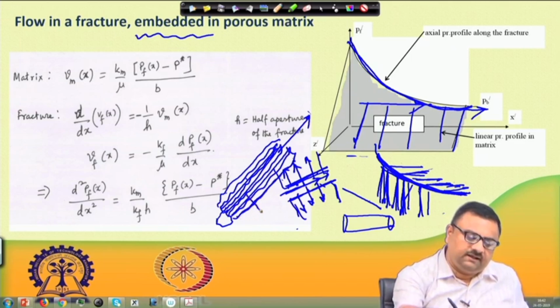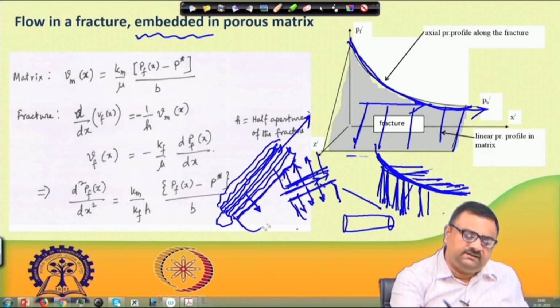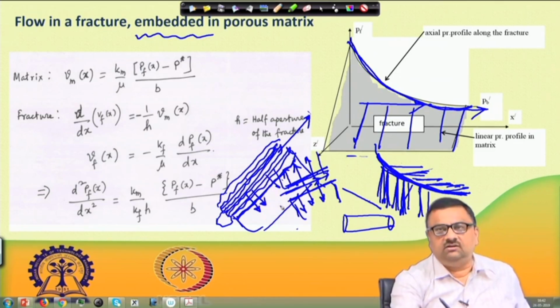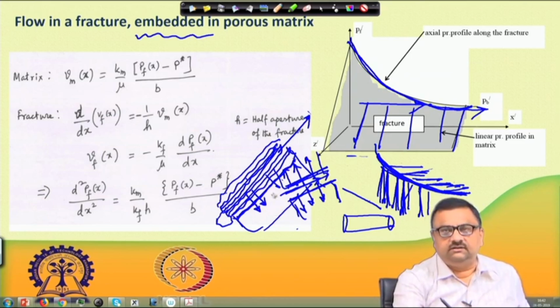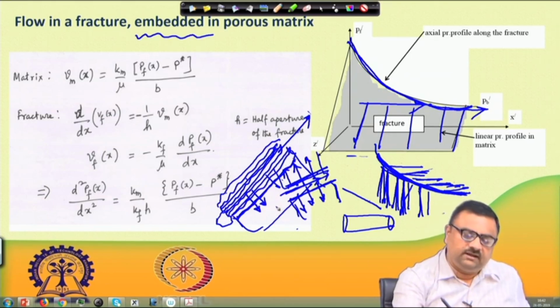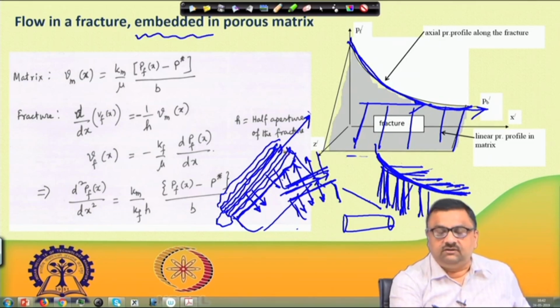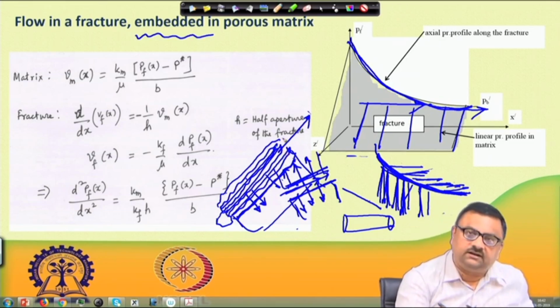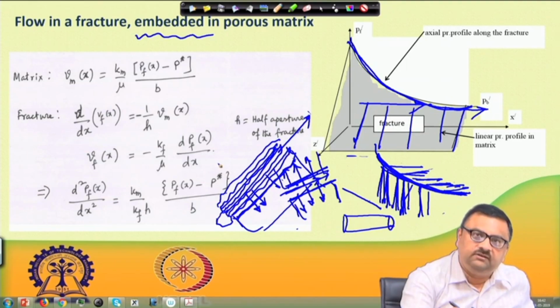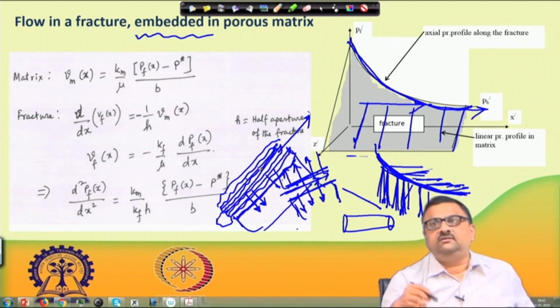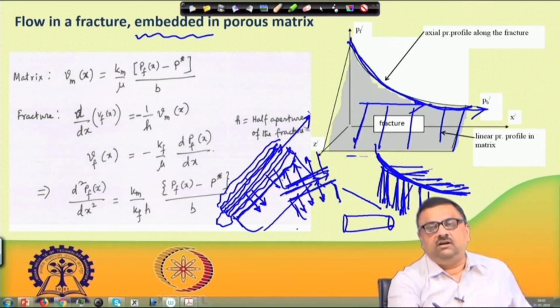So, one front is coming and getting into the porous medium. One has to look at this dispersion, which is just a classical dispersion of porous medium. It has nothing to do with the fracture. From a line source, fluid is entering and undergoing dispersion. One has all those longitudinal dispersion, DCT, etc., appearing here. But when it comes to the fracture, we do not have that possibility. On the other hand, when we have linear flow through the fracture only and no fluid going into the matrix, in that case there is truly a dispersion happening at the outlet end of the fracture.